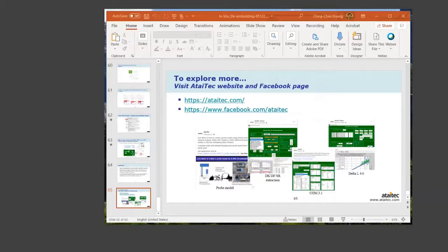And in other cases, you may want to embed from two sides, left and right sides, one at a time, because the left side and right side are different. Then you can go through this pause to skip. The first time you skip the left side, the second time you skip the right side. So there are many options you can do. You can take care of the active device here also. And there are many menu buttons here you can choose to plot TDR, to plot S parameter, etc.